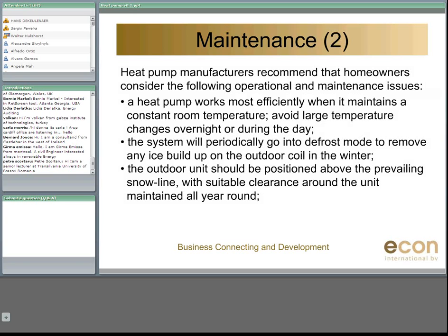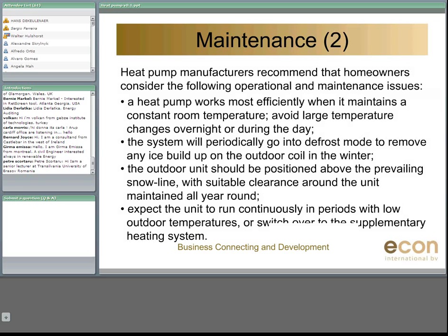Please also, as I mentioned before, note the snow line. If you're living in the northern part of Europe, you might have some snow over there, which can be very high. So please take into consideration that you have to place your outdoor unit at a higher location and not at the bottom of your house.